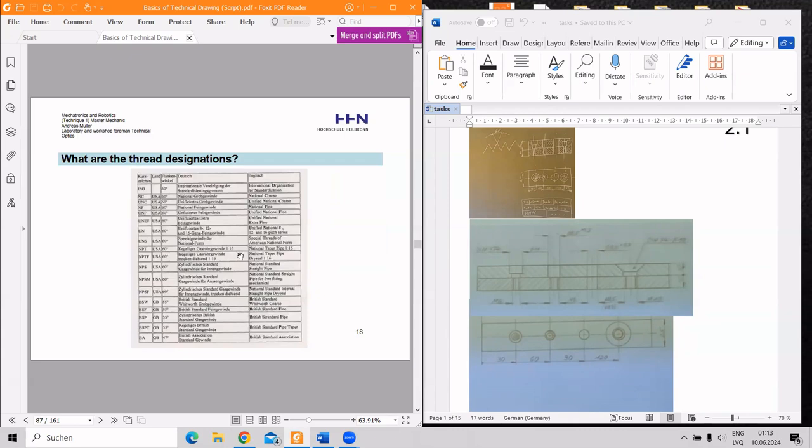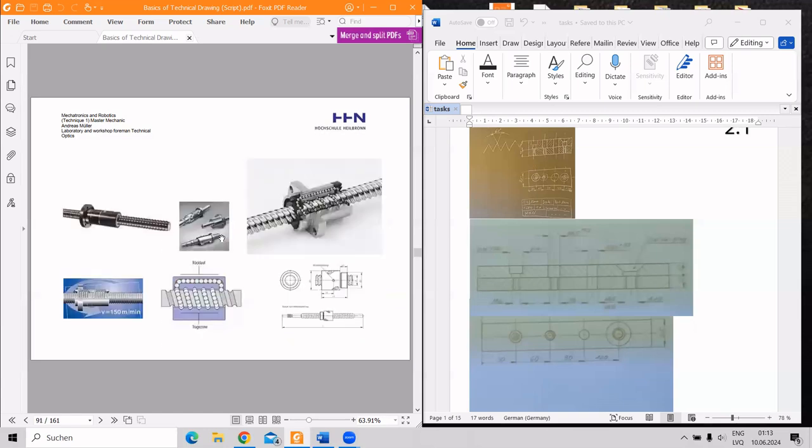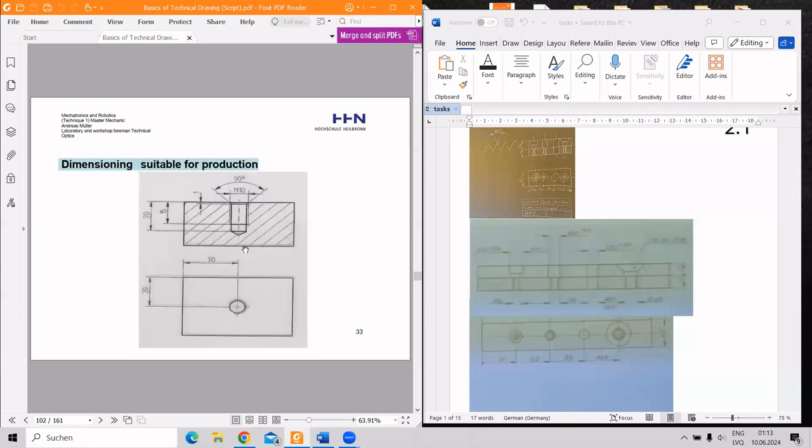We won't take into account the bolts and nuts, screws. Also, a way to designate a hole. We will use here a distance of 1 millimeter between the nominal and the outer line. And for a through hole, we'll use a circumference of 3/4, like this. So we'll also take a look then at the connection.